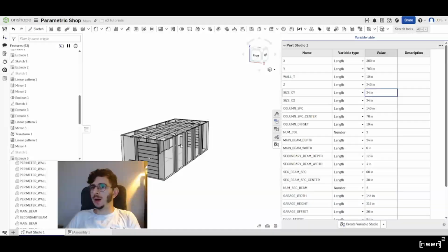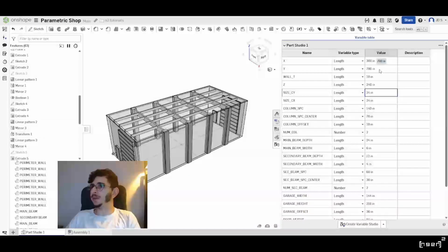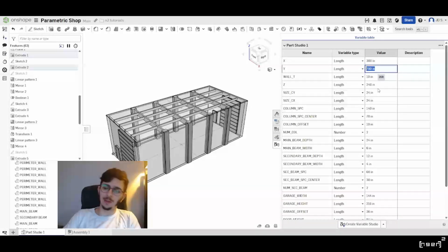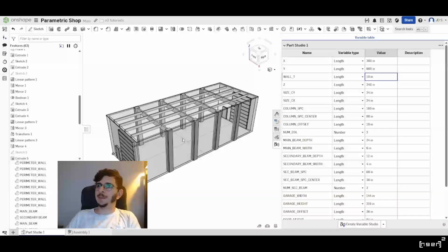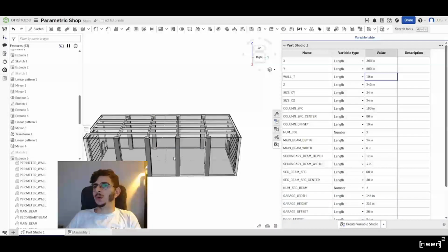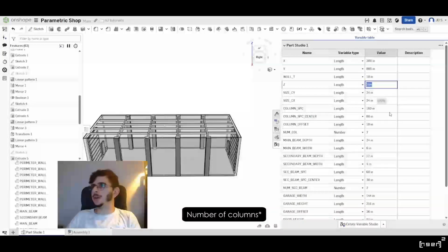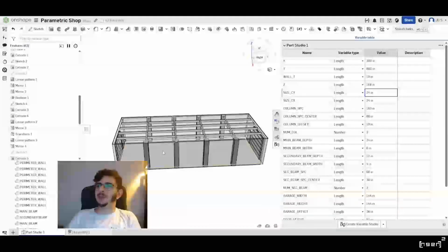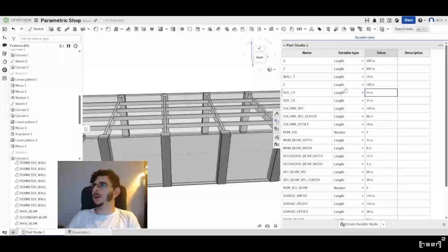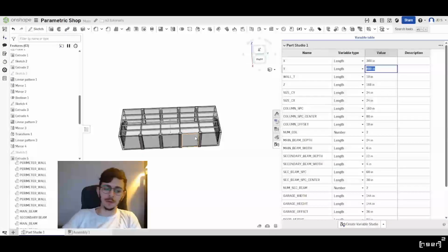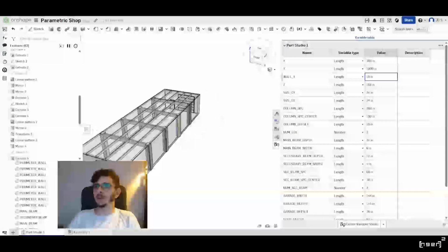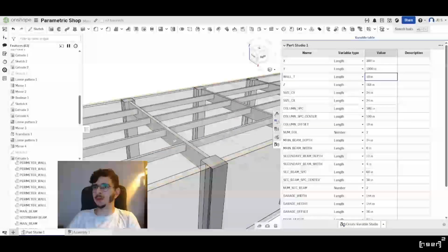But yeah, no, I'm good with how this is right now. Let's see if we go longer. The problem with going longer with this setup is you don't want to go too long with this spacing, because then you just have too few columns, and realistically you'd probably add another line or two or three or four of columns to meet that length and structure. We don't want to spread this structure out too thin.